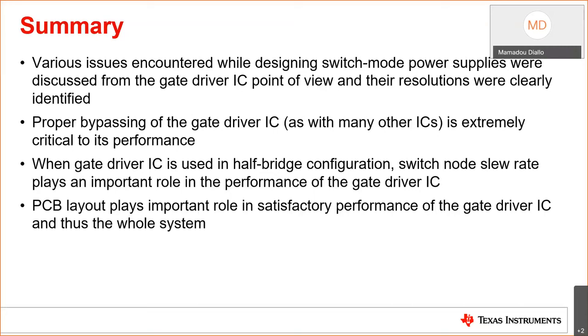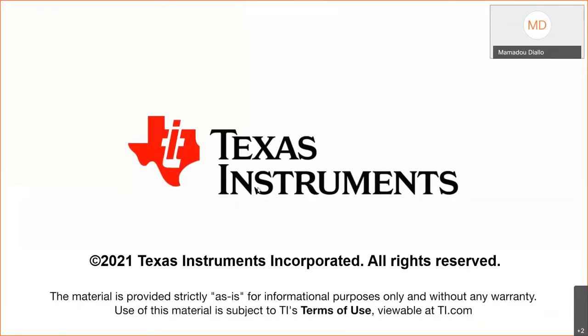And in summary as well, the PCB layout plays a critical role. So it is therefore important to make sure that you plan accordingly by separating the power stage from the input stage signals, and also making sure that you have adequate component placement on the PCB layout. Having said that, I'll go ahead and open it up for questions and feedback and any concerns.